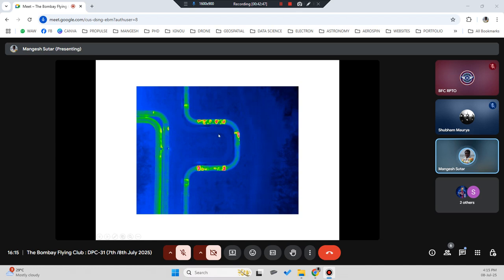So every time they get the information that this particular bend has gone faulty over the period, maybe down the line like 1 year or 2 years later, they just have to remove the couplings, change this piece and replace it with the new piece. That's it. Earlier, this was a single pipe, so it was very difficult to replace. When they did it the first time, they had to replace the entire length of the pipe with the particular shape. Later on they applied couplings at this location, and they just have to replace this particular portion of the pipe. That's it, nothing else they have to do.